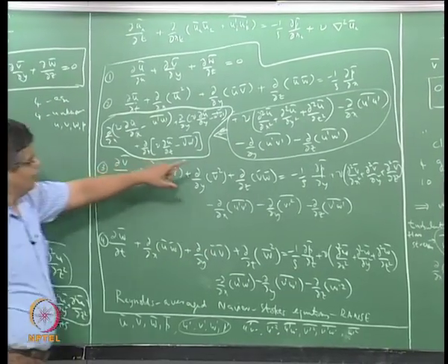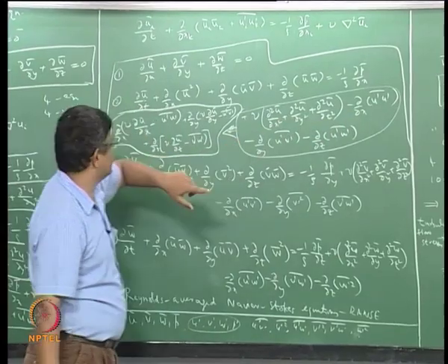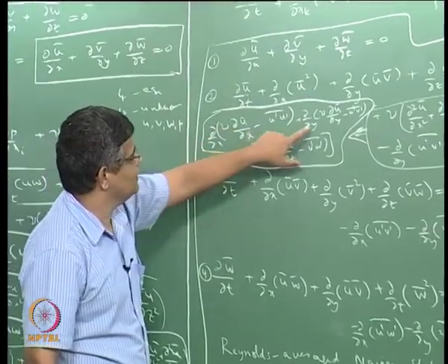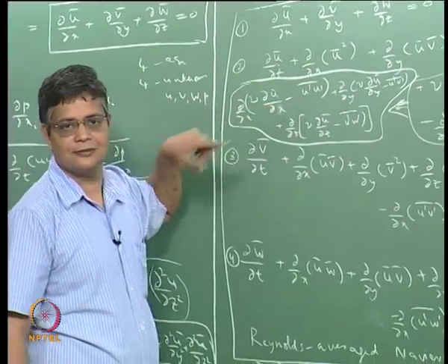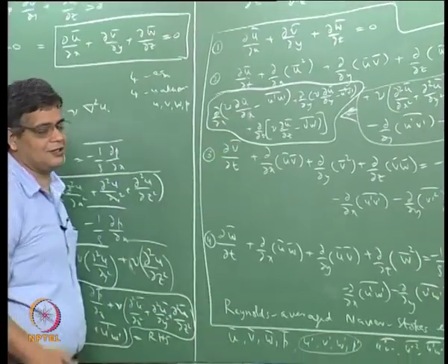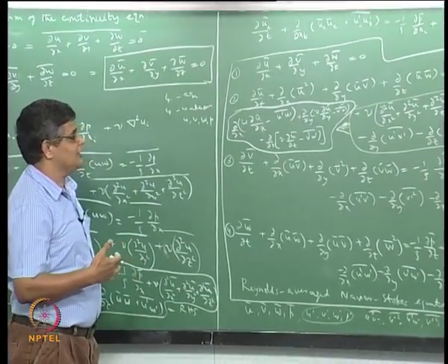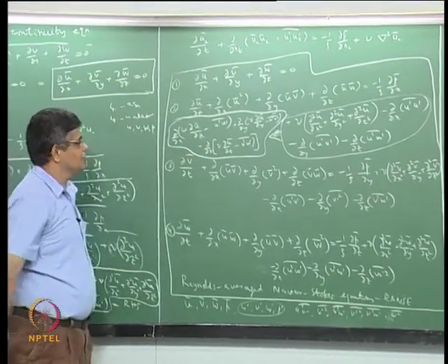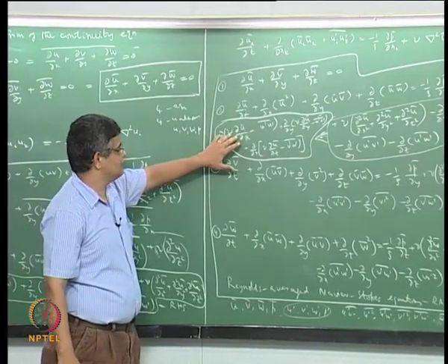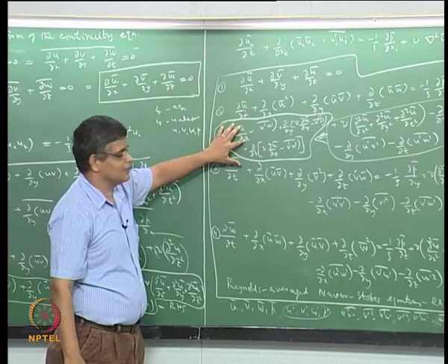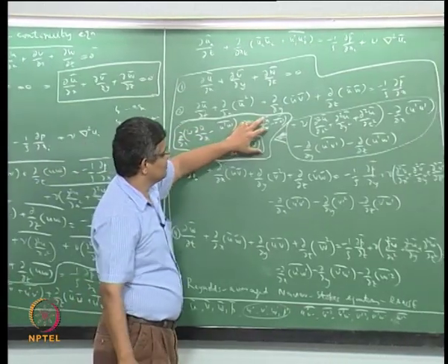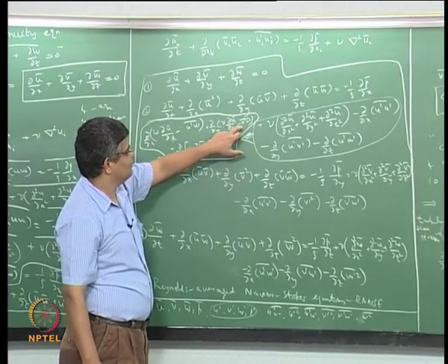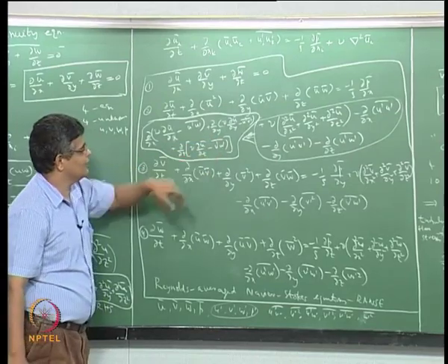and therefore these turbulent fluctuations, the time average quantities, are directly adding to the corresponding viscous stresses which are appearing here. And what are these viscous stresses? These can be considered as momentum flux terms associated with momentum transfer arising out of viscosity. So this is a momentum flux which is arising out of viscosity and velocity gradients in the x direction, and this is the velocity gradient in the y direction which is causing a momentum flux of the x direction, and similarly like this.